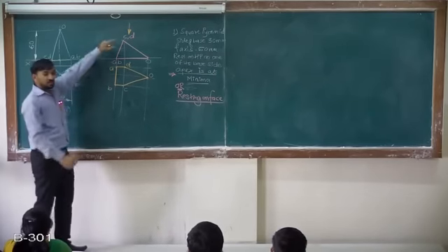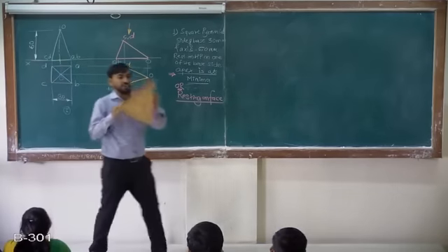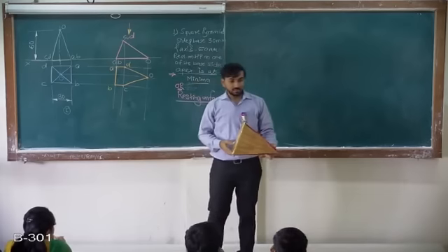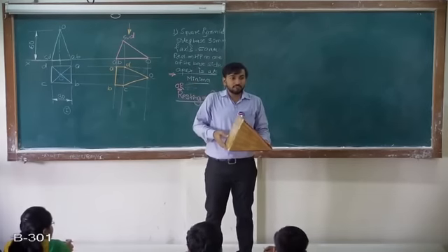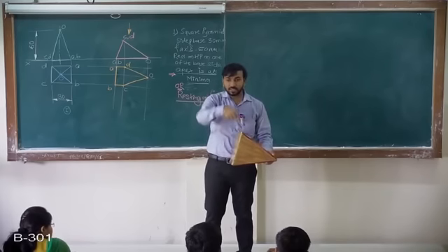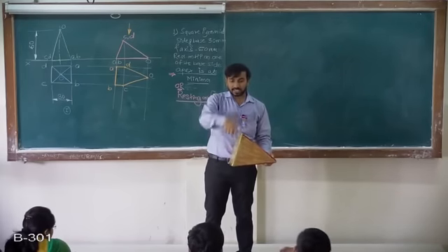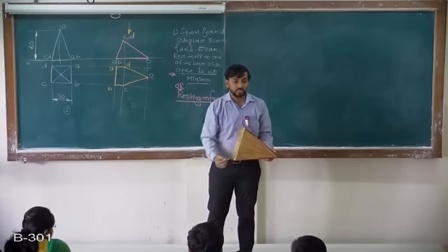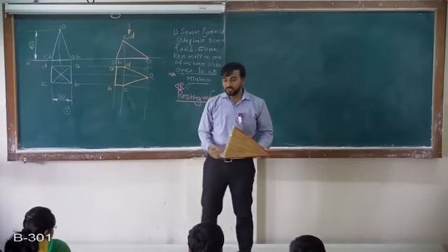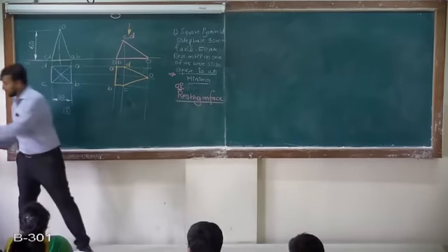So as you know for this problem, when it is resting on a face like this, you can see the base complete, all the four lines. Even though it is farthest, you can see it as an outer edge. Got it? So I need to draw all these lines visible. That is done.